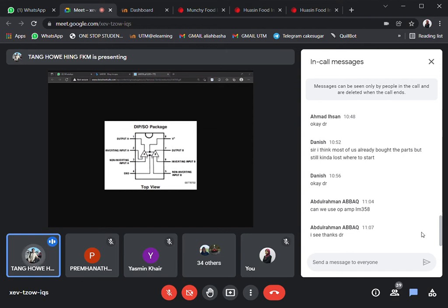So I would strongly recommend you use a dual power supply op-amp like TL072 or TL074. Okay, 72 meaning that it has 2 op-amps, 74 it will have 4 op-amps. So essentially all are the same. They use positive and negative power supply. Or 741, only 1 op-amp.